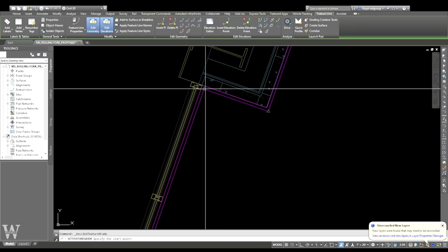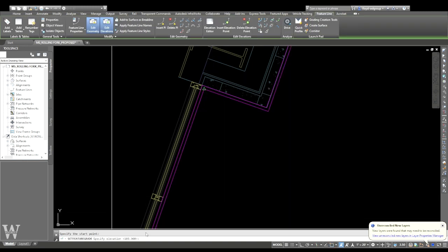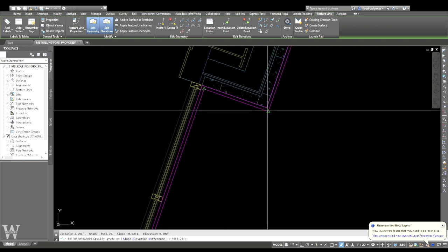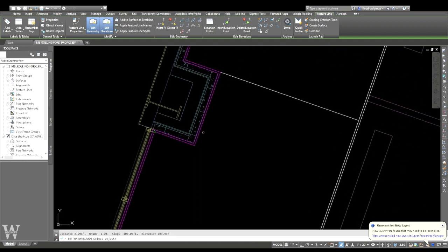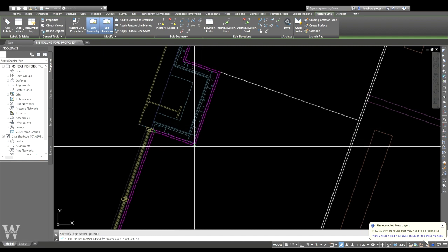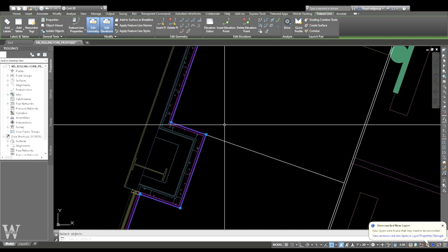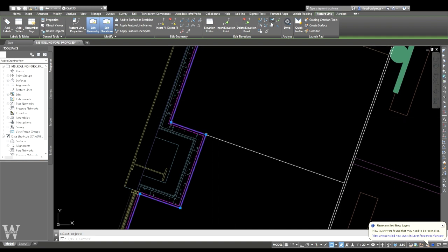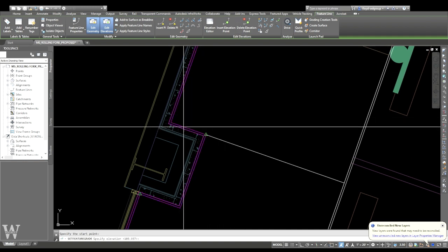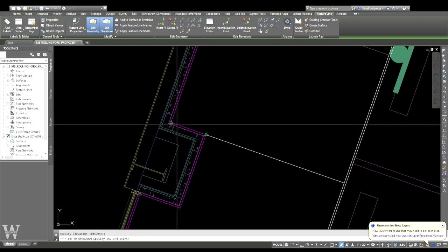I use this slope grade. It says elevation 103.96. That's exactly where I want to be. Then I want to grade, G for grade, -1 right here. And then I'm going to click this point, continue grade 0. And then I hit enter too many times, so it made me start over. Pick that elevation and grade 1.0.